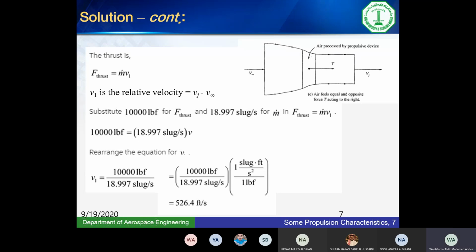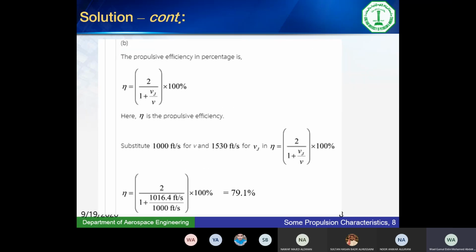So efficiency we defined last time as the generated power in the denominator and the useful power on top. What's the useful power? It's the thrust multiplied by the speed. This is what actually reached the aircraft. When we derived it last time, we made some simplifications and reached a final expression that I would like you to remember because it's a really simple one. Go back and check the derivation. It says the efficiency of any propulsive system that uses a jet is 2 over 1 plus V jet over V, which is V infinity, of course, times 100 because it's a ratio in percent. And that's it.